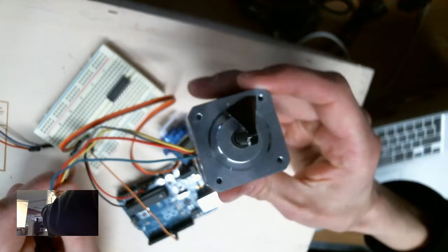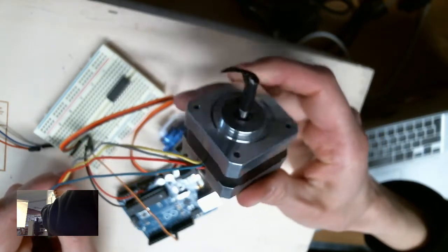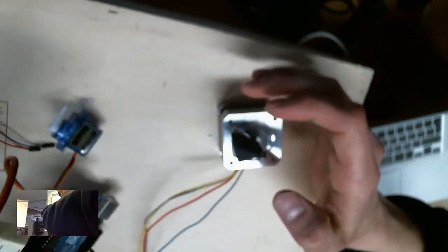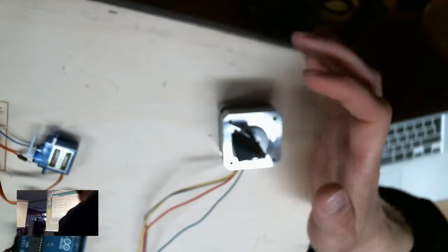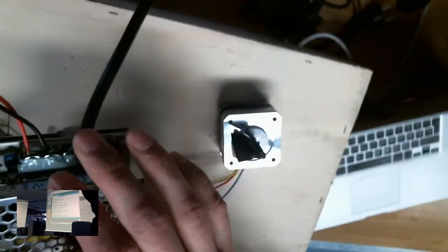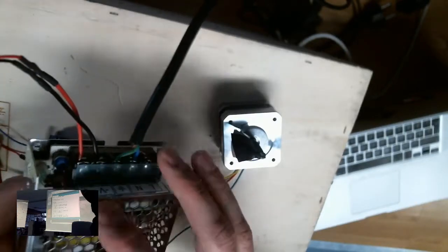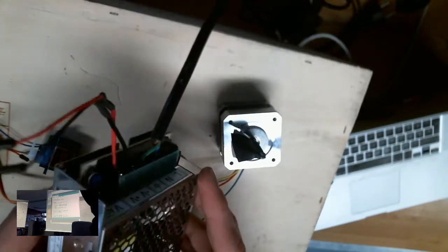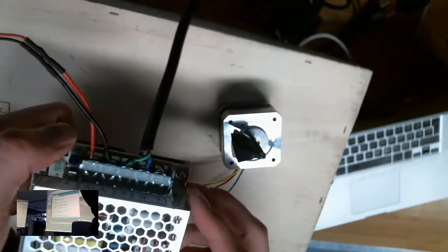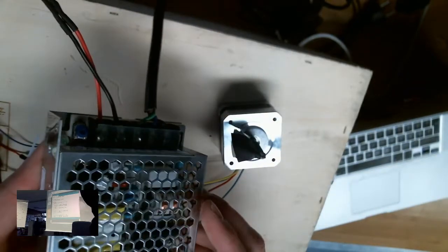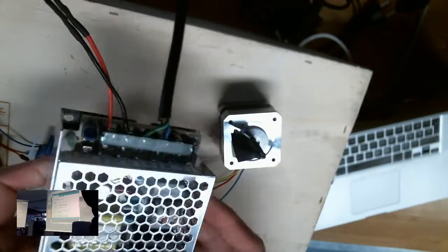Whenever you open up a 3D printer, you would see that these kinds of motors are used everywhere. And in order to drive those, you need this external power source. So in my case, I have this 12 volt power source. You would connect it to the AC current over here, and then you have these two outputs over there, plus and minus, and here you also have a potentiometer that allows you to control the output voltage, so it can be a little bit above 12 volts or a bit below.